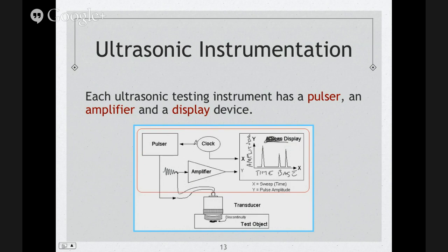So he sends the signal to the pulser, and when he does that, he starts counting and sending that information over to your display. The pulser comes down to your transducer. It hits that piezoelectric material, or element, or crystal, either name. That's going to create that wave.